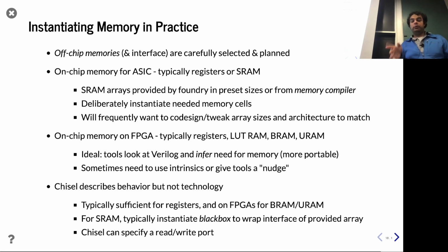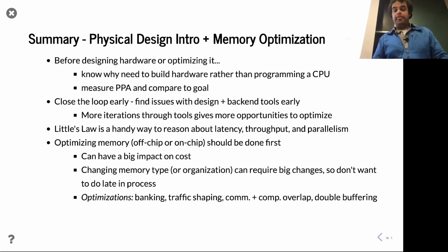Well, great. So yeah, when we're talking about memories like that, those are all sync read mems. So like a regular mem in Chisel, because it has 0 latency in terms of cycles to access it, that's usually going to be registers in most technologies. You can't really get that in SRAM. There are people who can do SRAM asynchronous reads that don't need to go to clocks, but that's pretty high end. So for the most part, yeah, if you're talking about SRAM, you're talking about sync read mem. Good question. Cool. Okay.